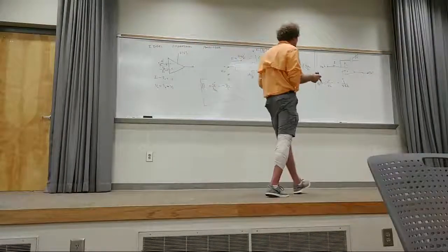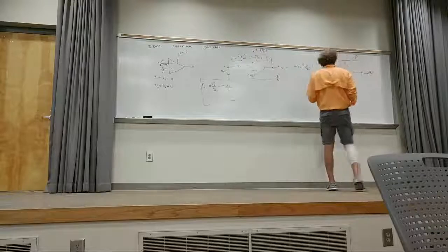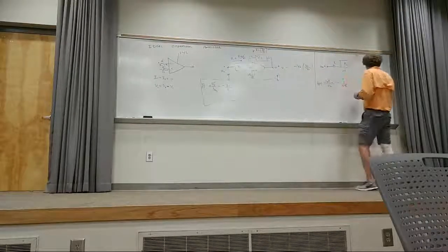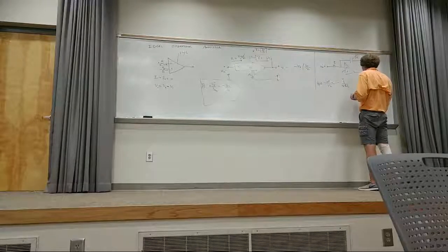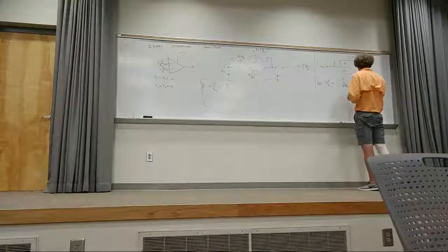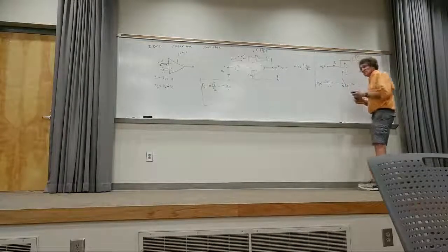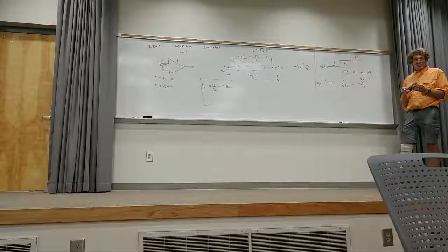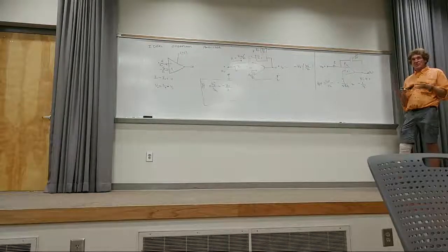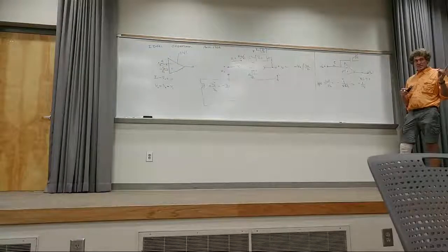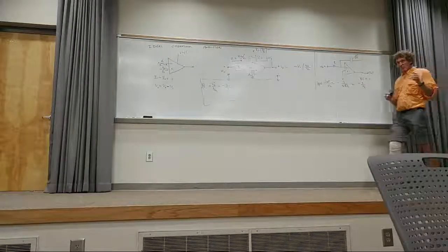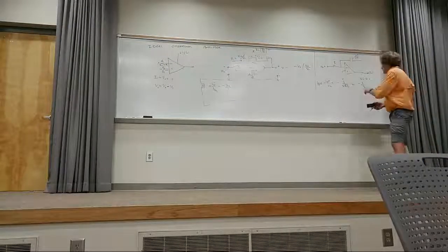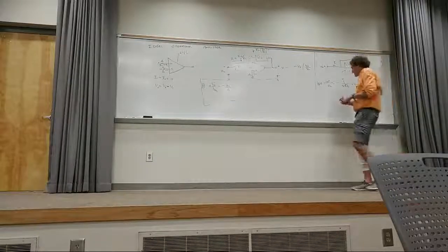Now that's equal to this. That's not quite what we want. And you'll notice if you make R times C equal to 1, you simply get minus 1 over S, right? Do you agree with me? So you can choose any values for RC you want. Now the next thing I'm going to do is this. I'm going to say, I want to just get rid of that negative. So then I can do this.